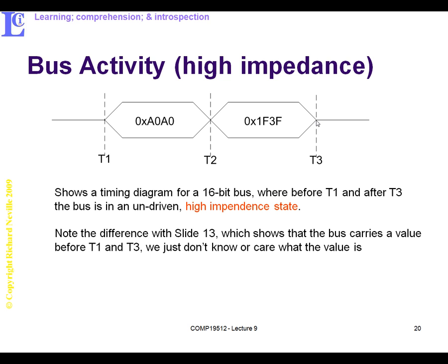So this means the address or data bus is set to high impedance, so nothing's driving it and it won't take current. But the major implication is that one or other of the devices can drive it when it's set into this state. Okay, and you should be able to notice the difference between this and the previous slide where we had cross-hatching. Particularly the values are exactly the same, but the device driving depiction in the diagram is different.